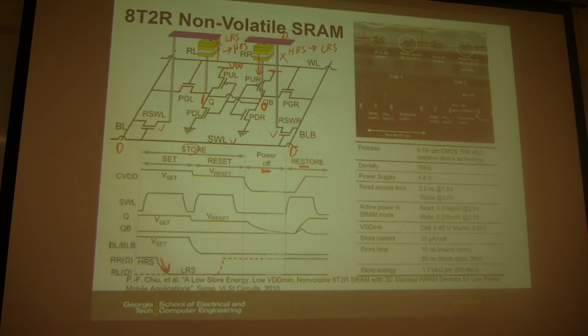So if you've got a logic chip and now you have to add the resistive component, it's going to start interfering with your metal layouts. No, because RRAM technology is CMOS compatible, right? Even when you do an RRAM array, your RRAM is on the metal layer and is compatible with CMOS fabrication.